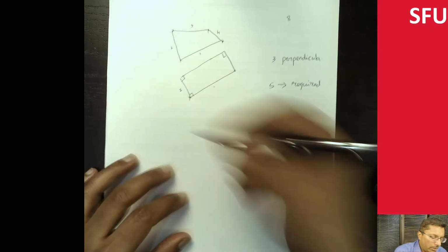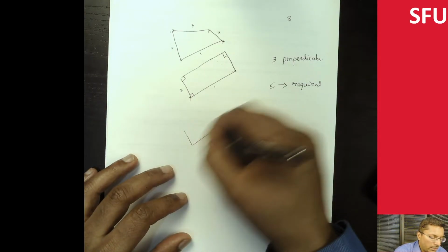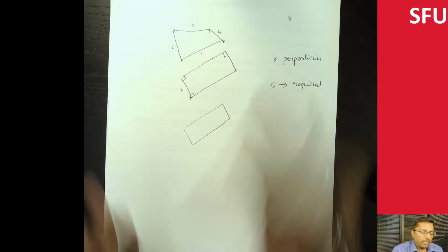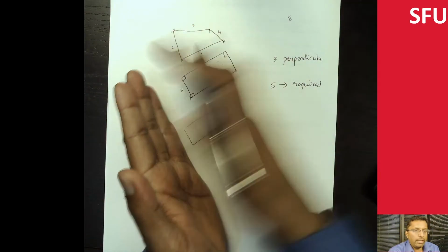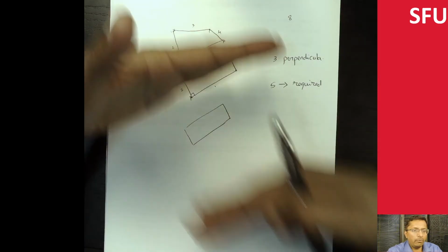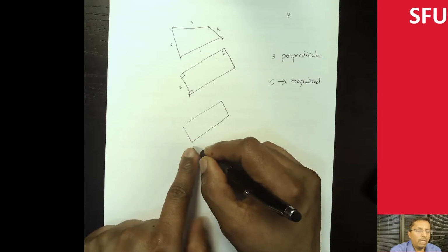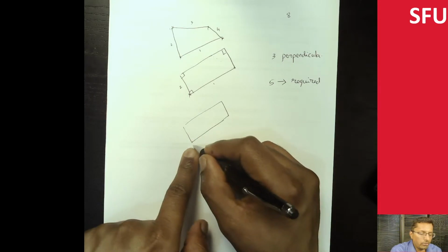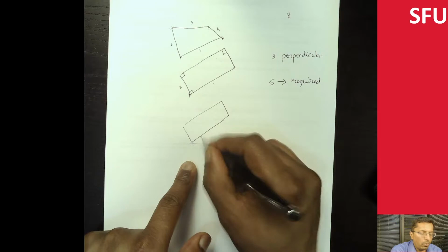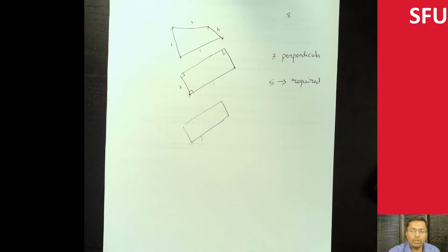So if I have a rectangle over here, I can define the constraints as follows. I can tell you the length and then the height of the rectangle. So those would be 2 constraints. And then I give you 2 coordinates for one of the locations over here. And then I need to give you the orientation of the rectangle itself. So that will be 5 constraints I can specify. You can do the same thing in different ways, but you will still end up requiring 5 constraints. So let's write this down in our sheet.